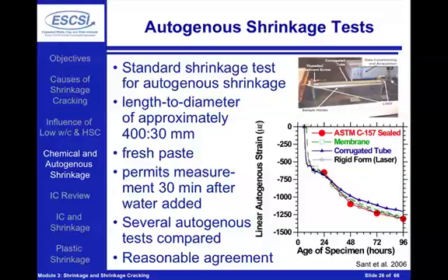So a fresh mortar, paste, or concrete can be placed in a tube like this while it's fresh. The ends can be sealed off, and then you can measure the volume change inside of this tube. Now, the real meaning of this test starts at about the time of set, and then you can measure the overall volume change as a function of time. And if you compare these tests and account for any of the differences or inconsistencies that may happen with leaking or temperature changes or things like that, once you've accounted for all those things, what you'll notice is all four of these approaches can give us a very, very similar value.